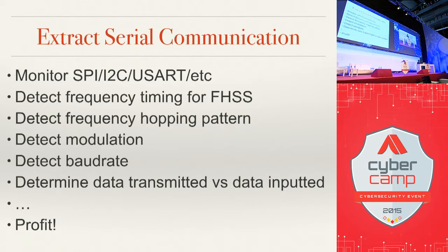Is that following a simple pseudo-random number generator? I can detect the modulation, because now that I know what chip it is, I can look at the data sheet for that chip, and I can look at everything about that chip. I'll know the baud rate, I'll know the modulation, and I can see all of the data being transmitted.